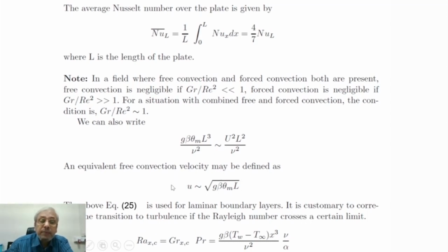So this gives an expression for free convective velocity, how a free convective or natural convection velocity can be created. If we know the volume coefficient of expansion, the temperature difference in the field, the distance between the two points through which this temperature difference is acting, and g, then we will be able to calculate the natural convective velocity.